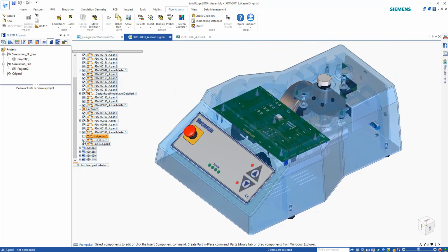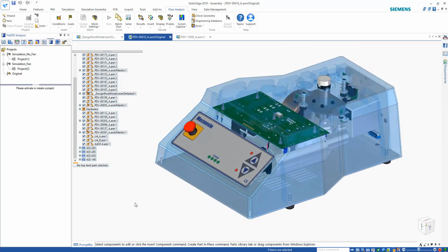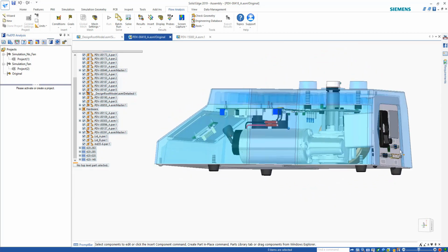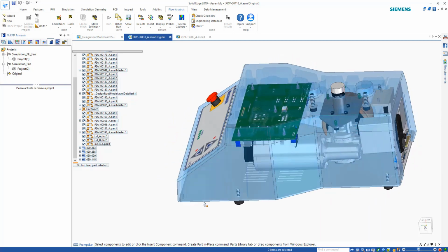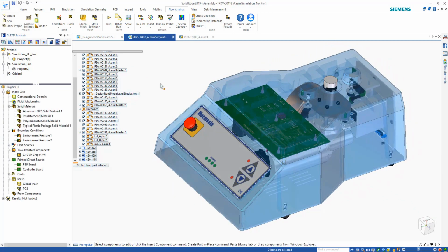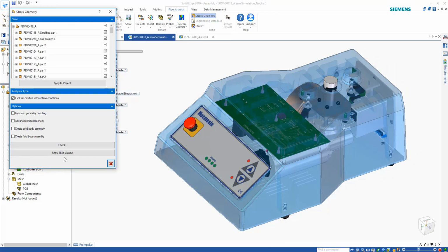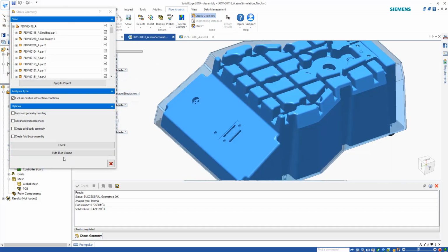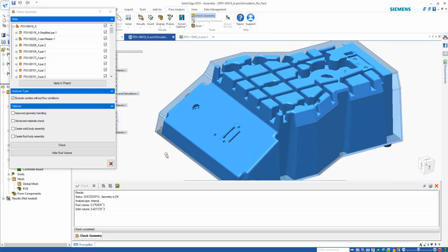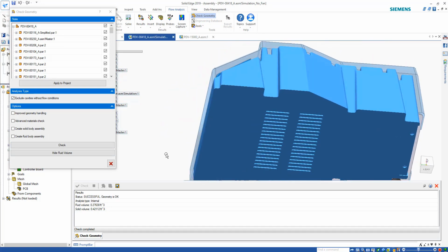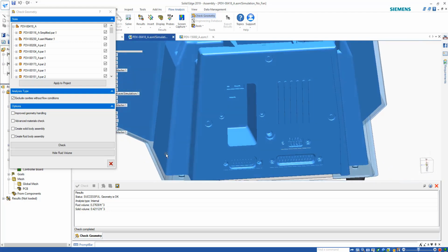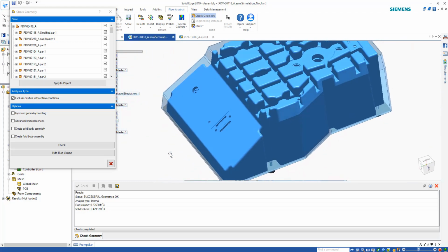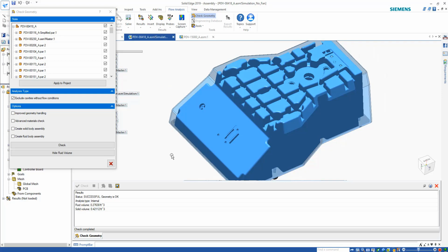Two extra lid parts are present, which close off the internal flow region and on which we can define boundary conditions. Using the FLOEFD check geometry, we can visualize the air region within the enclosure. The blue volume is the air occupation region, and the complex shape can be seen around the vents and the electrical connectors. This part does not have to be created manually. FLOEFD generates this automatically for an internal analysis.